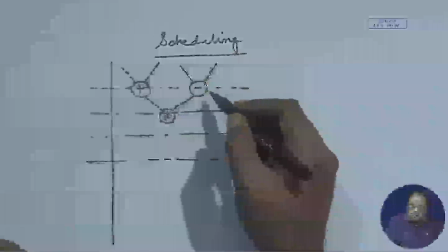If I want to have them done at the same control step, then of course I need a separate adder and a separate subtractor, or 2 ALUs. Then we come and do some multiplication. Now I could have done this in a different way. If I want to save on the number of adder subtractors, I could do the addition here and then do the subtraction here.